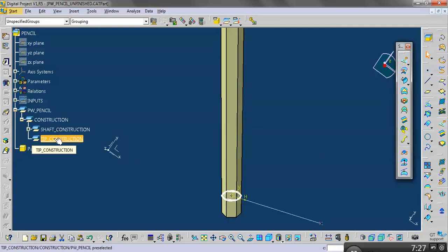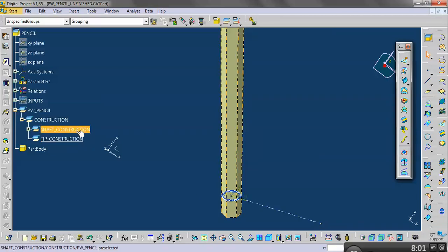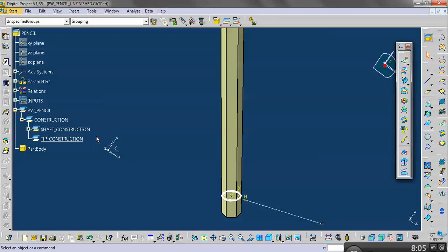When we start modeling tip construction, everything inside tip construction is going to be based on shaft construction, which is based on inputs. As we start going down and building some more surfaces and like the eraser and the eraser clip or whatever you want to call it, all that stuff is going to be based on the tip construction, shaft construction, and inputs. So the inputs trickle down through, and the hierarchy of geometry is represented in the tree structure and the nesting of geometric sets. Okay? So if you have tip construction above shaft construction, it'll work fine. I changed it. You can change it. I'm glad you did. It's not going to be a...